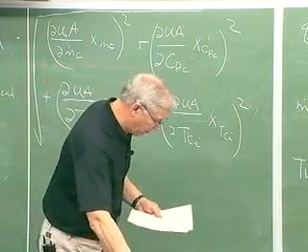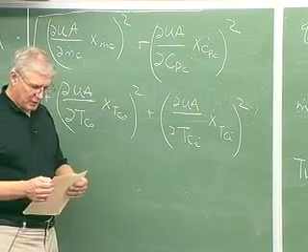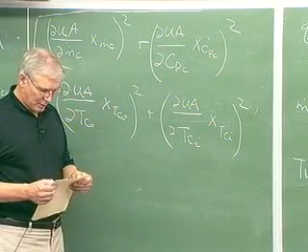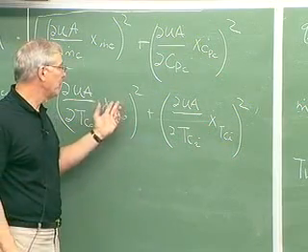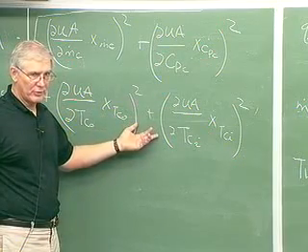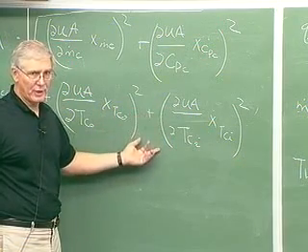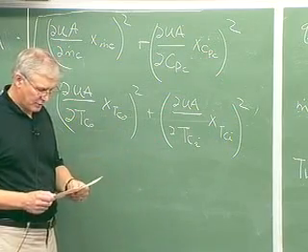The uncertainties for the thermistors and the flow rates are given in the lab write-up. The uncertainty in CP can be obtained using the uncertainties for temperature and the table. So you're going to look up CP in the table. You'll have a value for a certain temperature. Well, if you know the uncertainty of the temperature, then you can look on either side of that value and find out what the uncertainty in your CP value is.